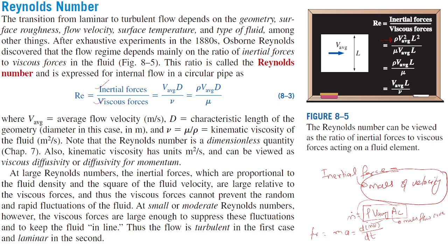Already you have the mass flow rate, that is this one. These things you have, and one velocity term comes up with this. What will happen? This will be rho V average squared, that is this velocity, and already velocity is here. But in terms of length, I want to write in terms of length. So okay, go back. So rho V average squared into area, having two length parameters, so L squared. So this is written here.